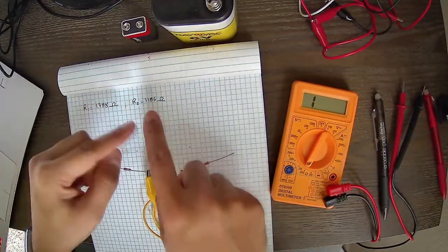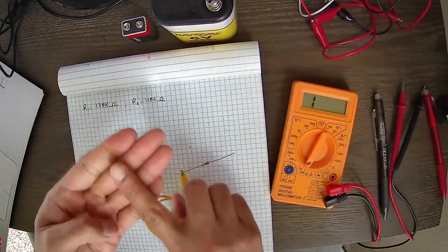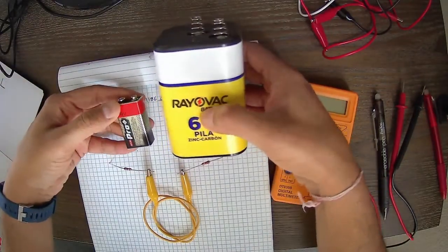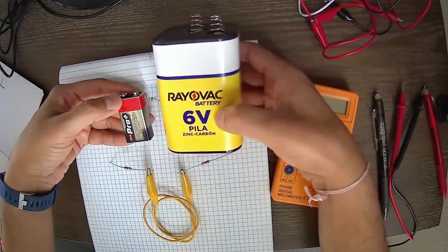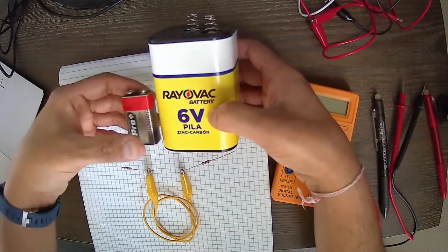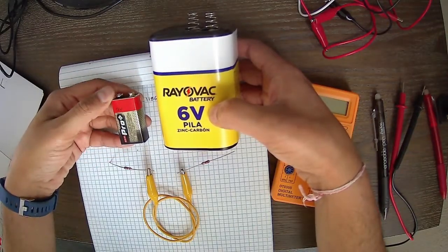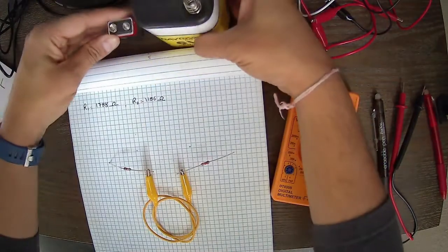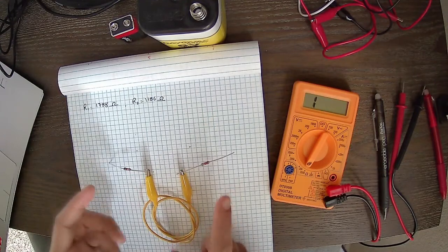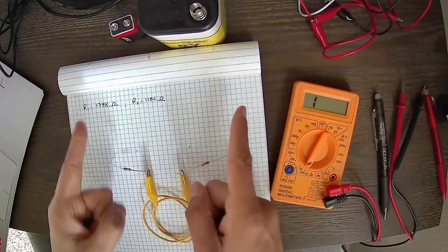And if we remember, the applied voltage is supposed to be 3, 6, 9 and 15 volts, correct? And looking at these two batteries, you probably guessed how we're going to connect them. But if you haven't, let's see how. So I have a 9 volt and a 6 volt, and I need 3 volt coming out of it. If you remember, this is kind of similar to the end of the video about Kirchhoff's voltage law, when we mentioned what happens if you flip the other battery, right? So what will be the total voltage between the two?